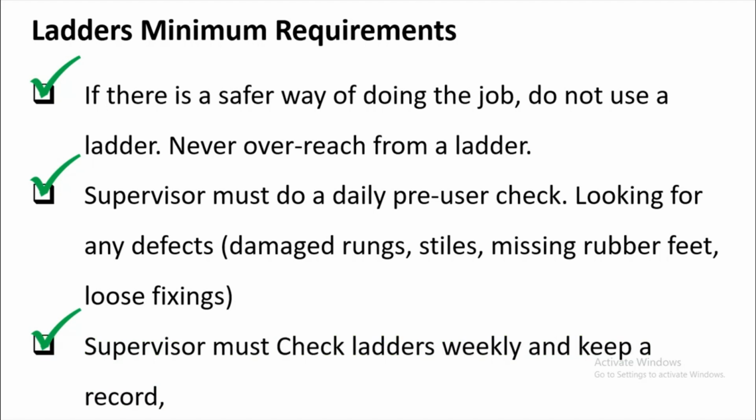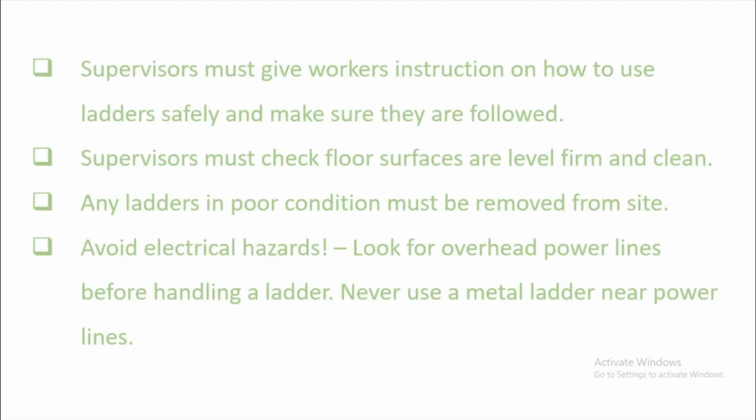Supervisor must check ladders weekly and keep a record. The pre-use check is different from the weekly check. Weekly means you are doing a comprehensive check of your ladder, to identify whether your ladder is still in good condition or in bad condition. Remember, if you find that the ladder is damaged, immediately remove it from service and tag it unsafe to use.